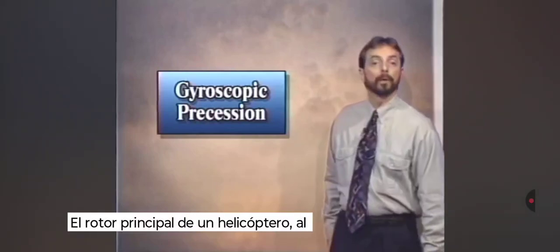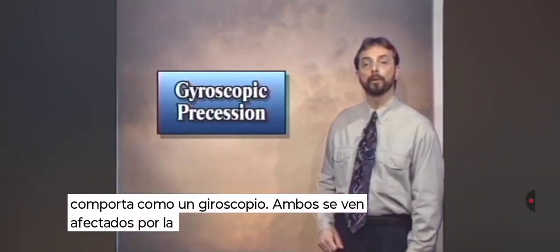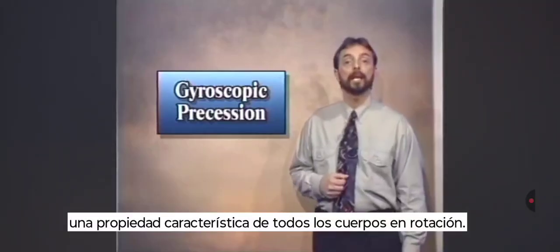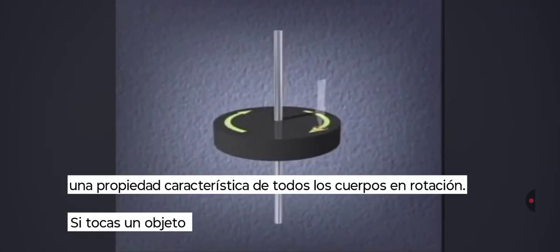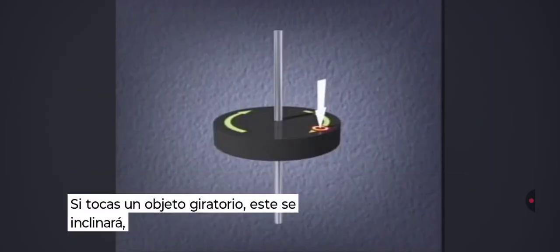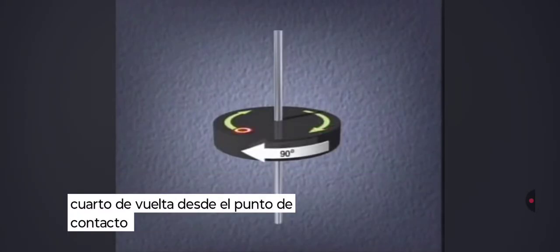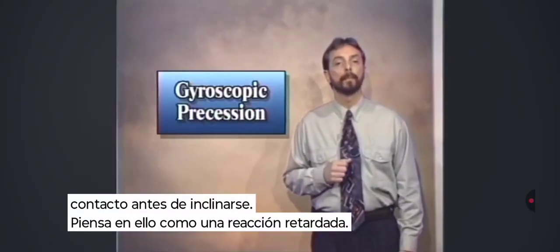The spinning main rotor of a helicopter behaves like a gyroscope. Both are affected by a property called precession, a characteristic of all rotating bodies. Take a look at this simple example. If you touch a spinning object, it will tilt. But the rotating object must make another quarter turn from where you touched it before it tilts. Think of it as a delayed reaction.